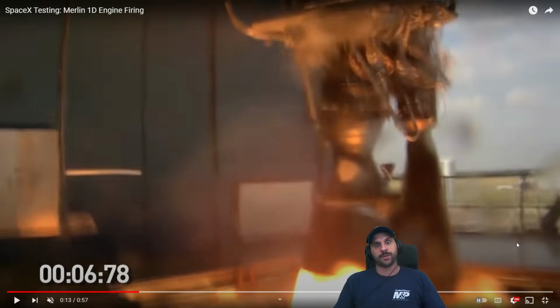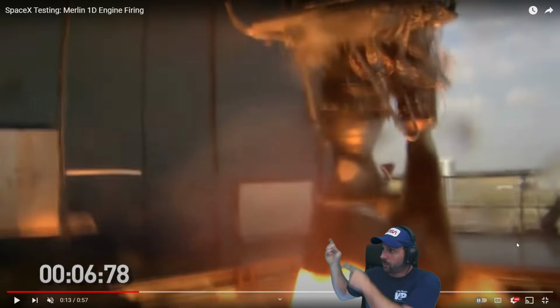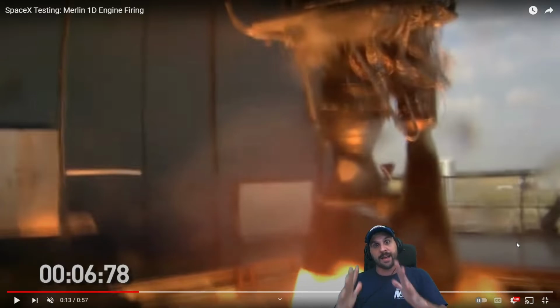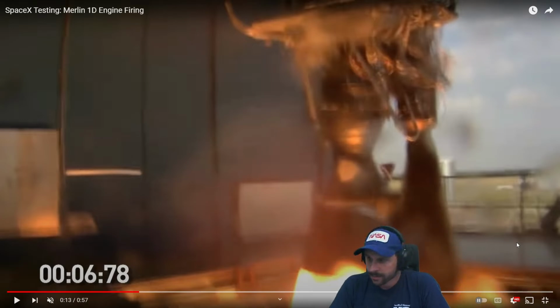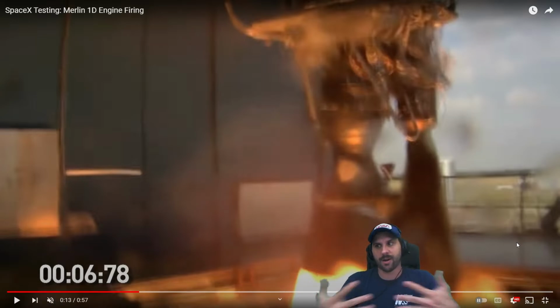Or, if they're using a fully cryogenic propellant like liquid hydrogen or liquid methane, a lot of rocket engines run the liquid fuel through the nozzle first on the outside through a cooling channel to cool the nozzle and heat up the propellant so they burn better. Diesel, RP1, Jet A, they're all brothers.